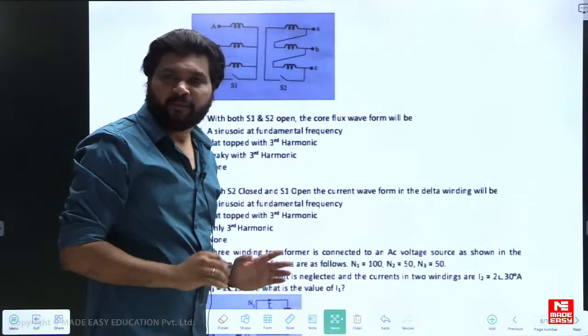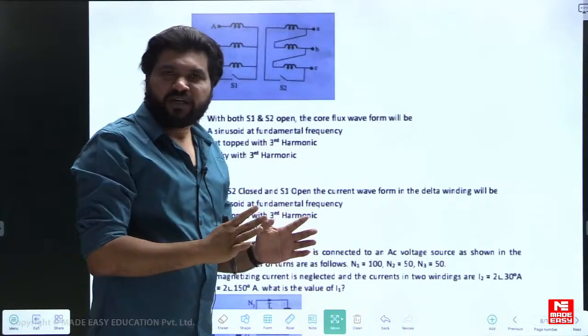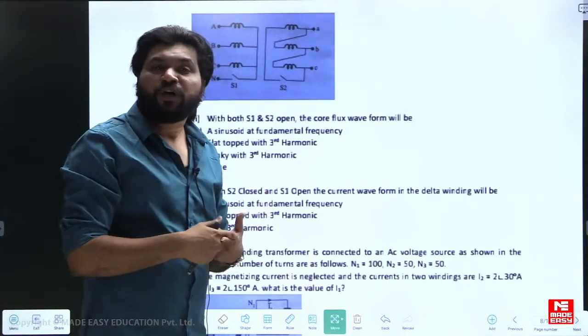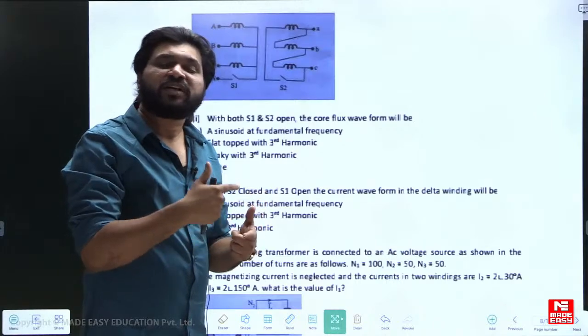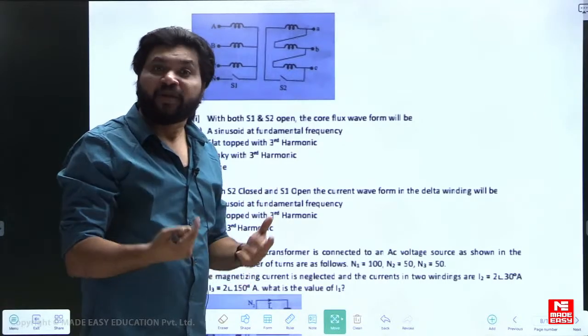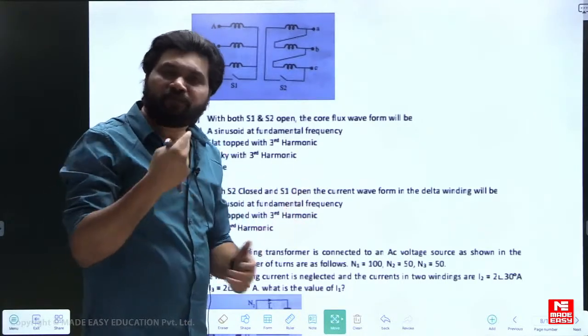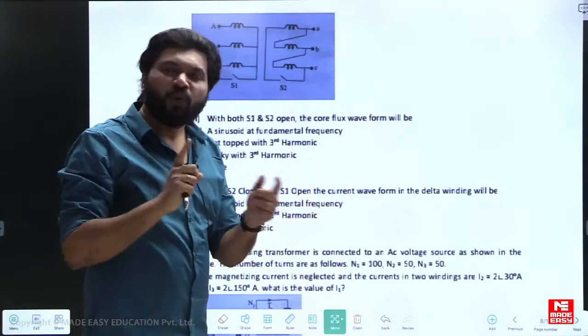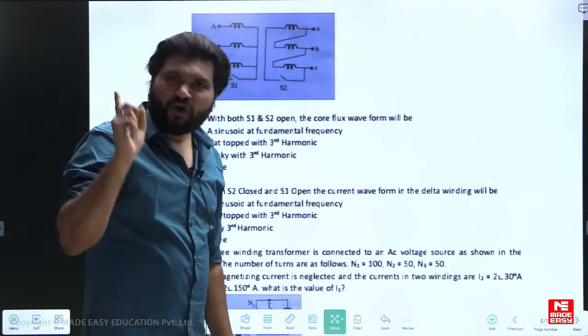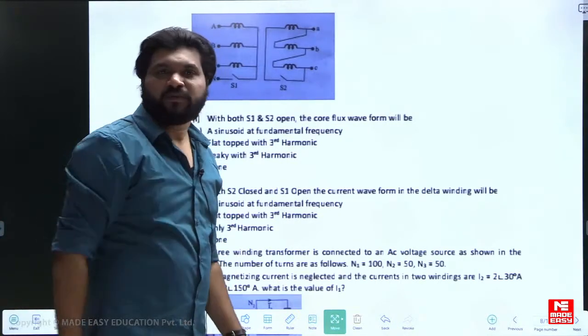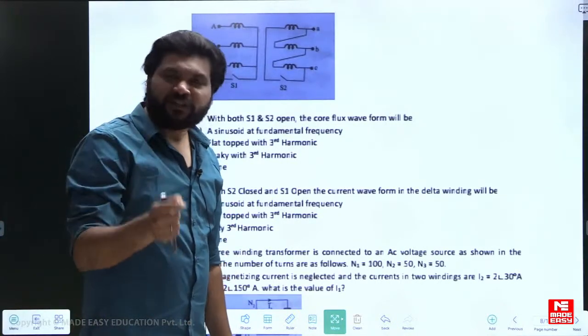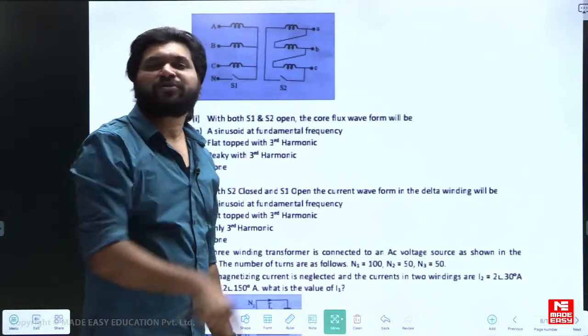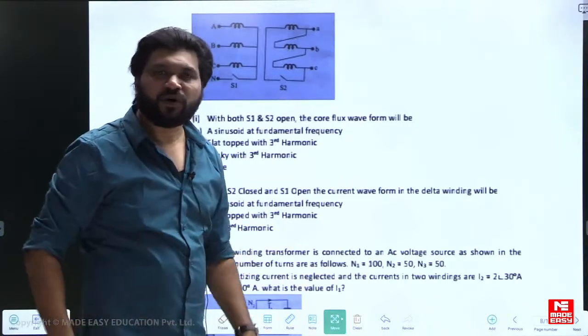First I am talking, when voltages are not sinusoidal, third harmonic component voltage existence will produce third harmonic current. If the windings support to circulate, automatically this current will make the current drawn non-sinusoidal. If current becomes non-sinusoidal, automatically flux becomes sinusoidal. That's the agreement in the excitation phenomena concept.